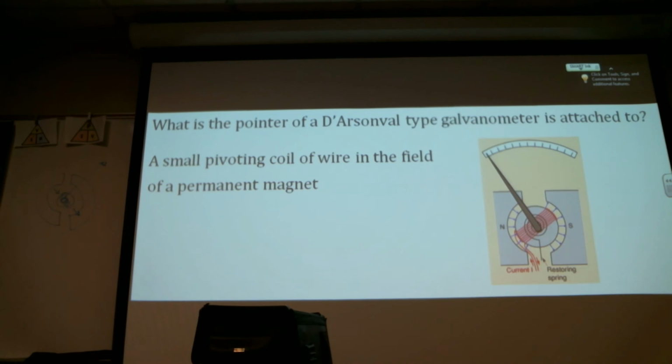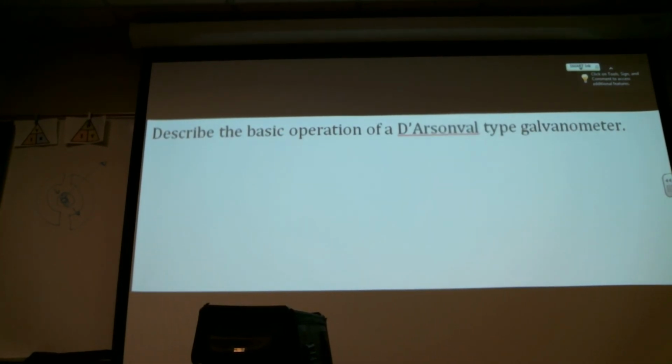So if we had a shunt resistor while we're using it, when it's slamming, it would stop that? Yeah, but the meter has shunt resistors inside already. So that's what you're doing when you're making selections, is you're rotating through various types of shunt resistors. We're going to see that. I think it's in part of the description today or my presentation.